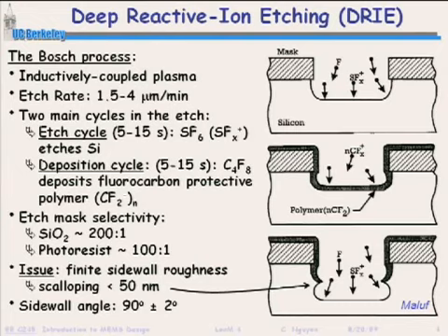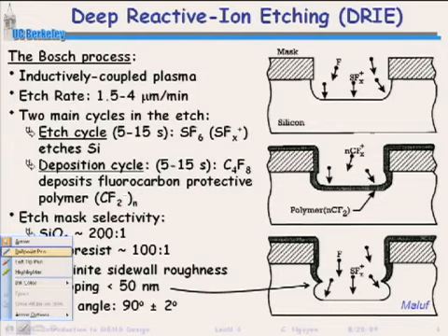So you mean there's some, but that's what's happening actually. When you switch to this cycle here, the ions come in and they blast off that polymer at the bottom. So in this cycle here, you would coat this part with a polymer. This part here would be coated with a polymer, and this part would also be coated, except these ions come in and they break up that polymer. So you already have something where you coat the edges with the polymer, then you come in and you break up that polymer there. Okay, there's many variants of this as well.